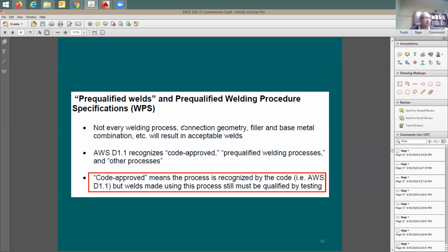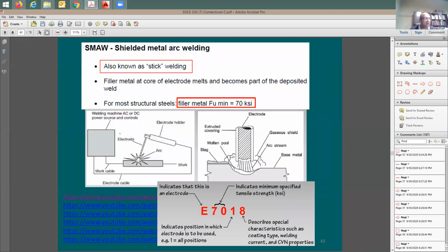But welding, you need to do the fusion. Fusion means that you're going to be mixing the welding material and the base material, which means the steel, together. And there is more than one method of doing it. So what you're trying to do here is heat this up, create lots of heat at this location, and then provide the welding material in here so that you do this fusion.